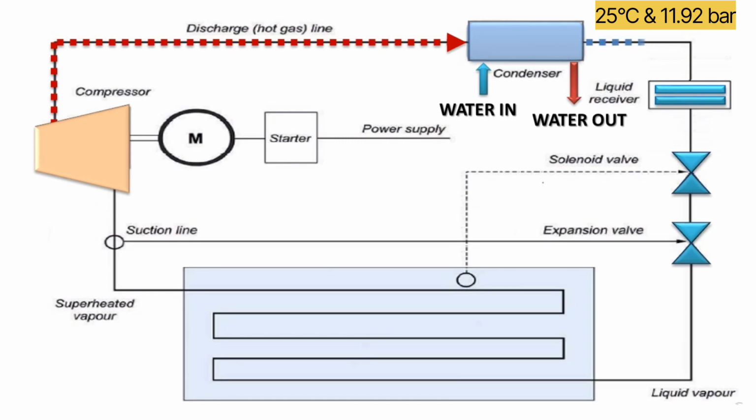Now the refrigerant fluid is passed through the filter dryer. The purpose of the filter dryer is to ensure that the refrigerant system stays clean and dry. So, this filter dryer will remove contaminants including moisture, dirt and acids. The subcooled liquid then goes further to the expansion valve.